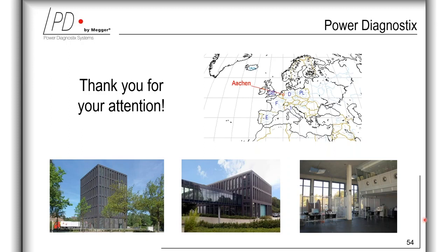So classical systems are transformers, power transformers, distribution transformers, rotating machines, motors, cables, GIS, air-insulated switchgears, and so on. But today we also find PD in small electric drives, in wind turbine systems, in solar panel foils, for instance, just to name a few. So to answer the question, we find partial discharge today in all electrical equipment with high electrical fields.